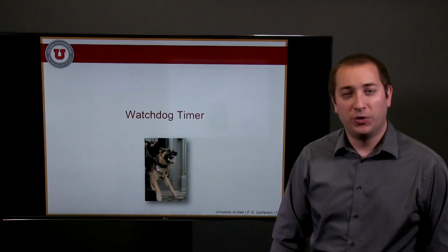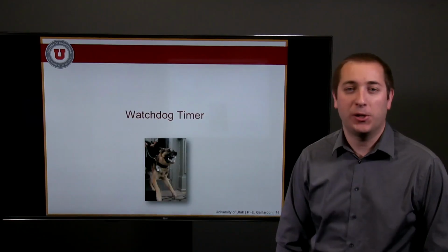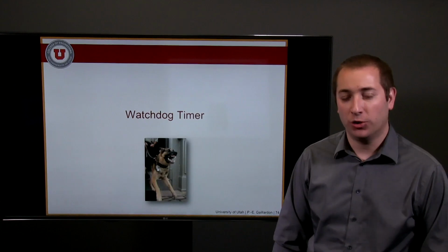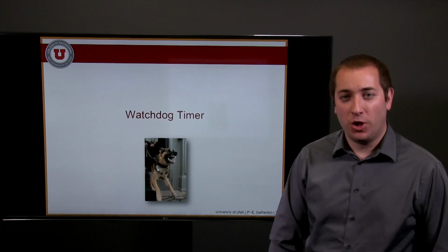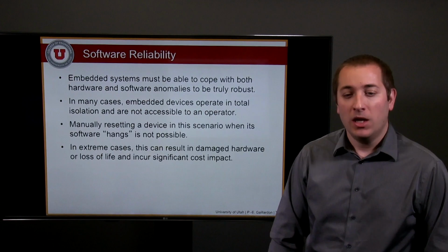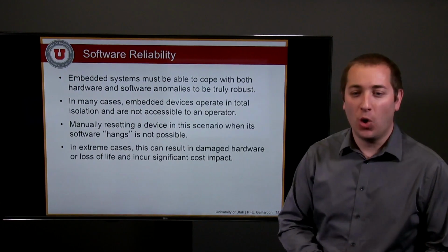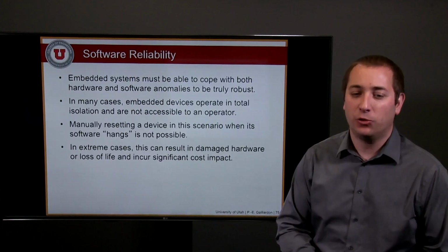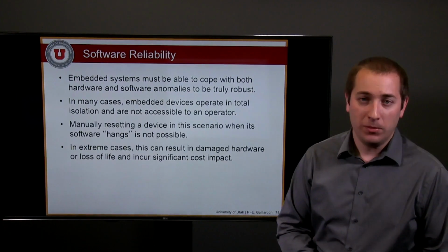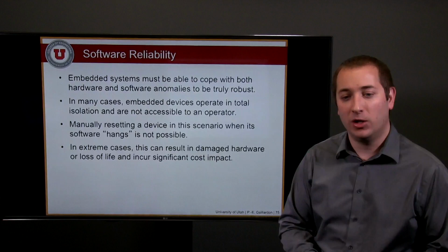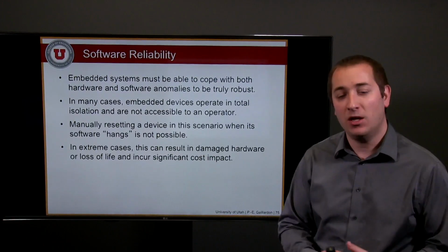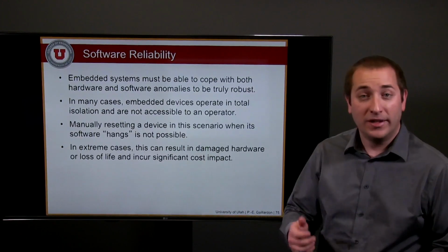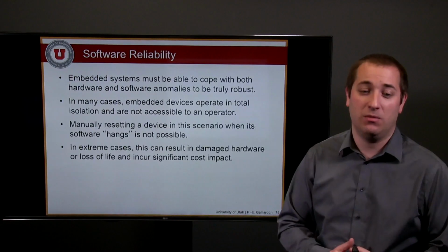I would like now to discuss a very important and peculiar timer function on our microcontroller, which is called the Watchdog timer. In embedded systems, you have to cope with potential hardware and software anomalies and be extremely robust. Because in many cases, embedded systems will operate in total isolation and not be accessible to an operator that can actually come and reset your system.